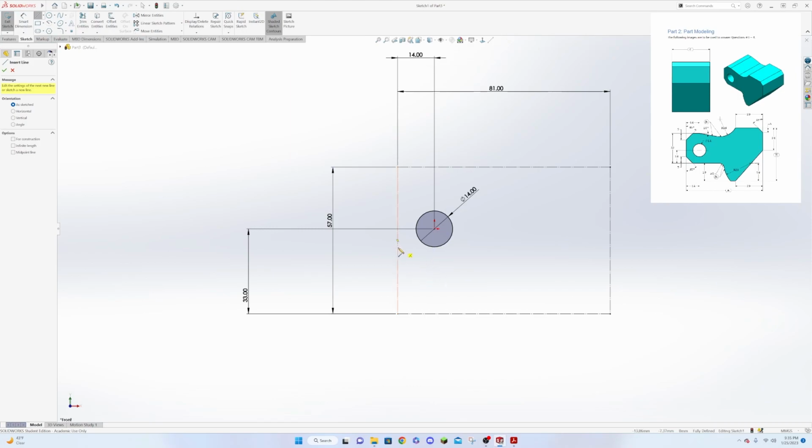So we're going to start off of that line a little bit. We're going to go here, and then we're going to go at roughly a 45-degree angle, a little short, straight over. Now you can see some things here it's already doing. It's already saying, hey, just by drawing something I accidentally created a 45-degree angle. And you can see that with the yellow lines. Right now we're going to say that's okay because it's supposed to be a 45, but you just need to be careful when you're doing that.